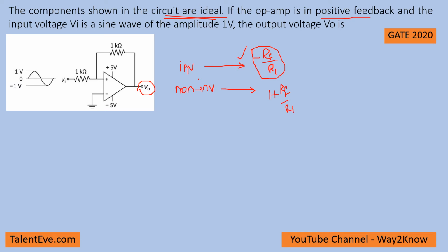But what happens is the output is fed back continuously to the input, because the output is also positive, right? When input is positive, output is positive in a non-inverting configuration. So output is fed back continuously, and the input increases with respect to this gain, and it saturates. Okay, so the main difference is that if a non-inverting configuration op-amp is used, when input is applied, it saturates.